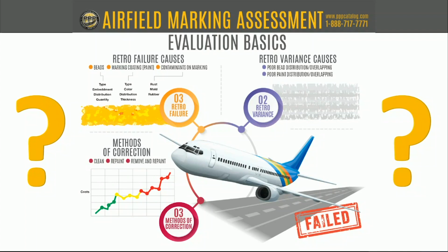So you just have to pay attention to those things, and you might have to change a tip once in a while. For a 12-inch line, depending on all those variables, I try to start right around a 631, 633. Very often I'm going maybe a mile an hour to get enough paint down. I know that makes an airless line a little ragged on the edges, but I actually like that. I'm looking for some texture in the paint film. I want to see almost like a fruit peel look, like an orange or a grapefruit. It should ripple a little bit.